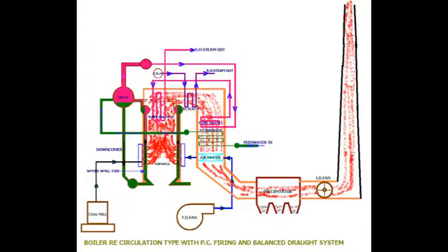Besides that, gradually concern for the environment evolved, and the question of how to arrest dust particles and toxic materials from the flue gas came up. So electrostatic precipitators, mechanical dust collectors, fabric filters, and selective catalytic reactors and non-selective catalytic reactors were introduced for control of SOx and NOx.